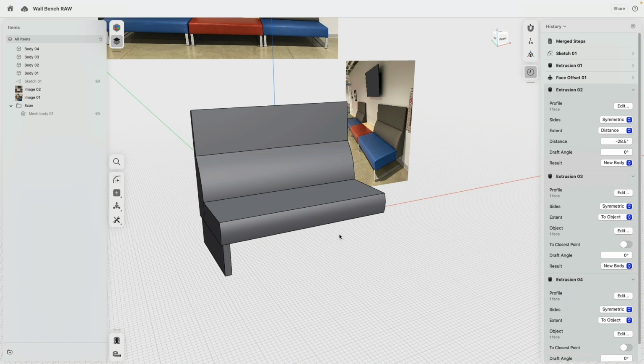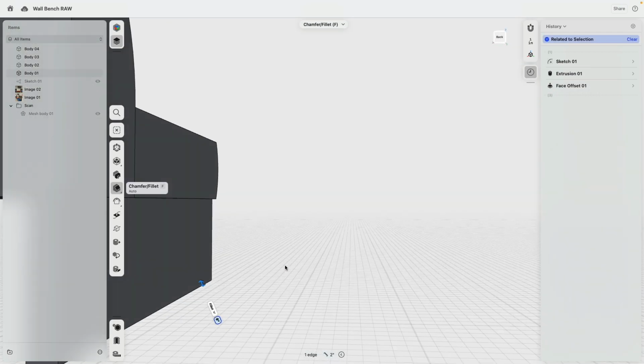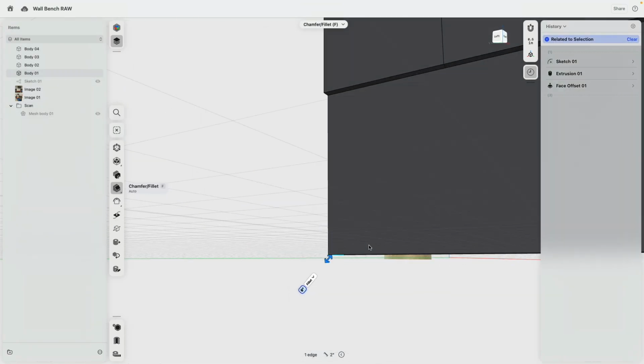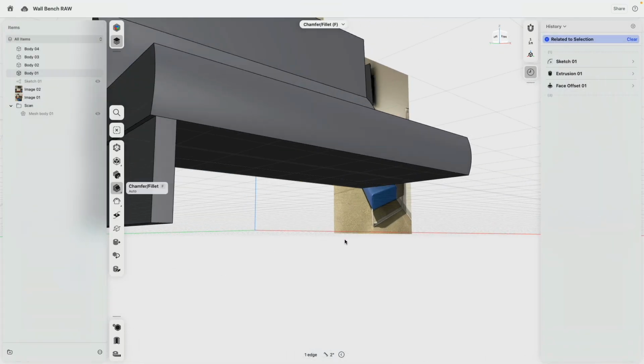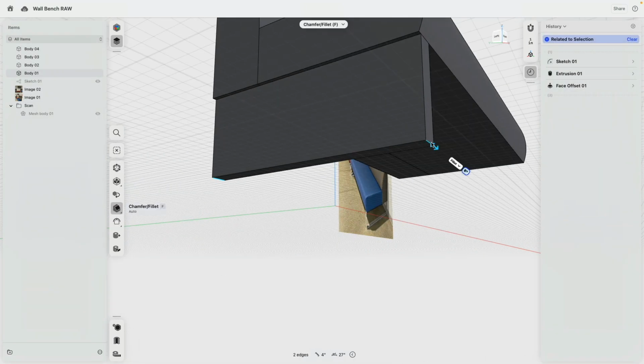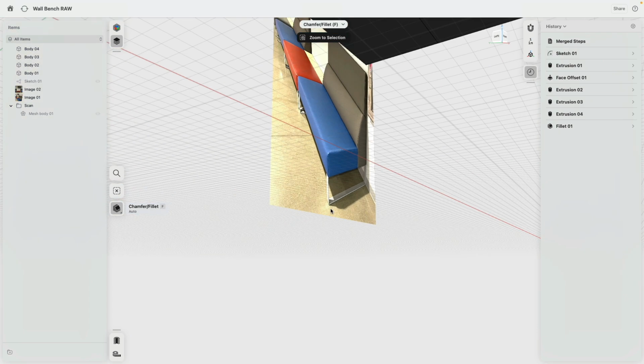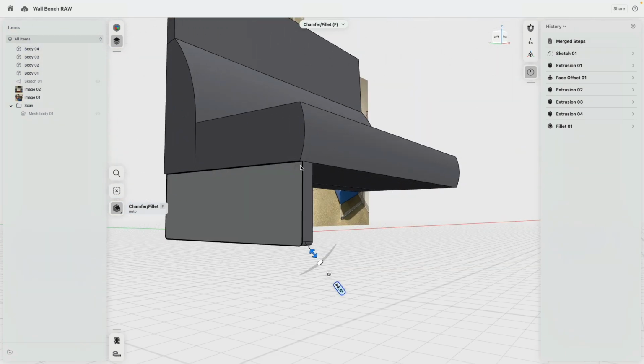Okay. We can now continue defining everything. So the next logical step would be to round these edges. So I have left mouse button and shift click, select those. Half an inch. Remember in the photo, this looks really tiny. Okay, so let's keep it that way.